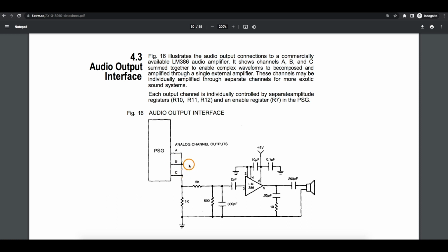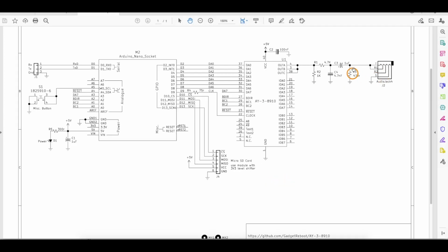Especially with this being square wave generated audio, we want to limit our upper frequencies here, so we're just really getting the audio that we intend. Then we have a series DC block capacitor to send audio out. That's essentially what I'm doing here, although I ended up with this resistor way over here. I think I had seen some other reference circuits set up more like this. And maybe this could be considered an advantage in some cases because it helps give a ground reference when plugging in some other audio instead of this capacitor directly blocking DC. Maybe that's not always desirable, but it seems okay for what I'm doing.